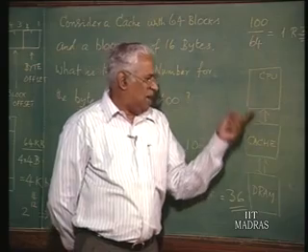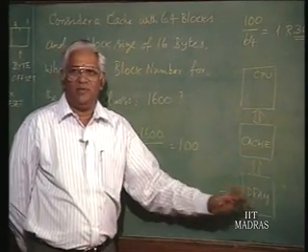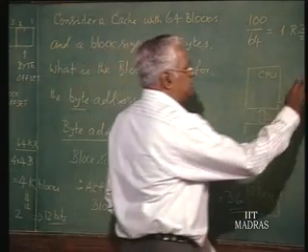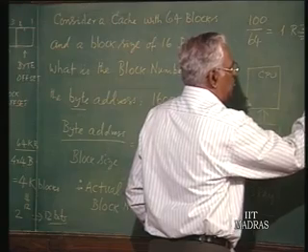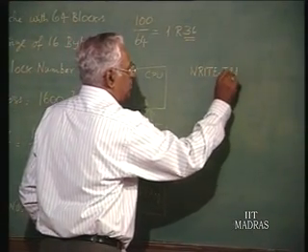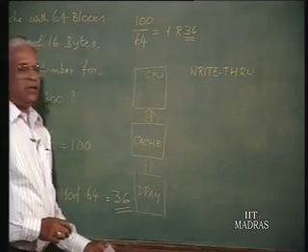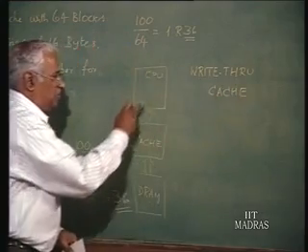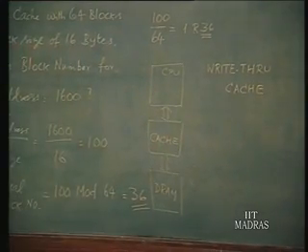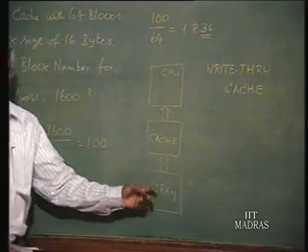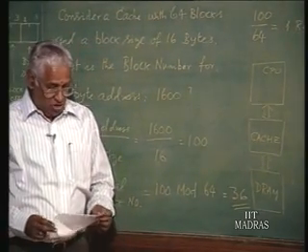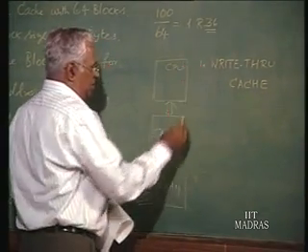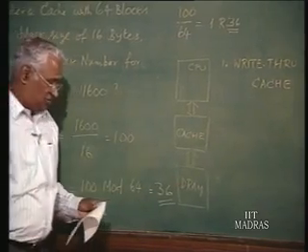So, one thing is, as it writes into the cache, it writes into the DRAM, do not mind about the speed, then it is called a write through cache. A write through, that is, as the CPU writes into the cache, the DRAM contents also will be modified or updated. So, in which case we talk about having a write through cache. So, you have seen whenever DRAM contents are also written when cache is written.